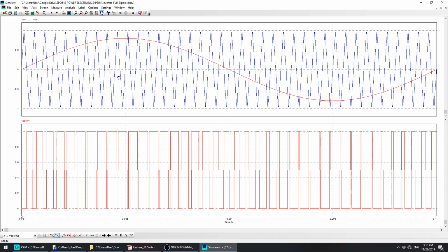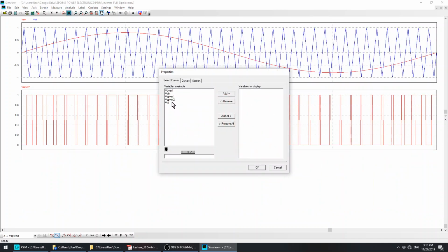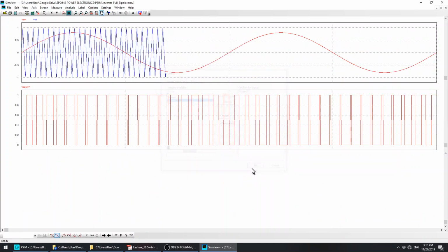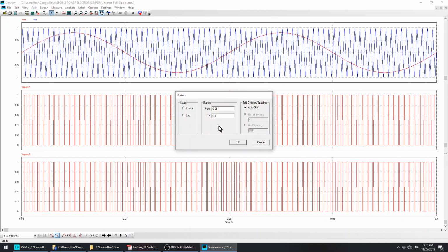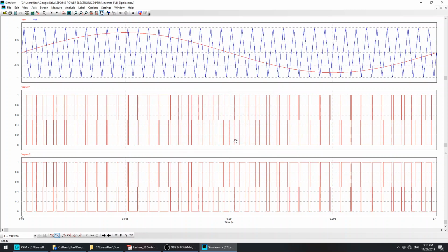And this will be SPWM1, which is the switching signal. This is only the switching signal to the two diagonal switches, S1 and S2. And if I add another screen here, SPWM2 will be the inverting version of the original output of the first comparator.